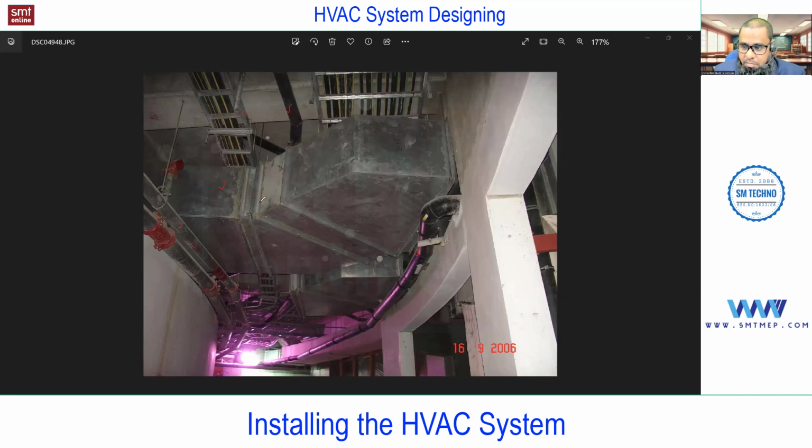That means why the firefighting lines are below the cable trays. Now your question is related to position, right? Okay, so you see, first of all, this cable tray is above the duct so that if any condensation happens on the duct, it will not lead to a short circuit. This is from a safety point of view. This is a standard practice, but in actual practice, you may find the cable tray running below the duct, because of coordination issues, because of such site conditions.